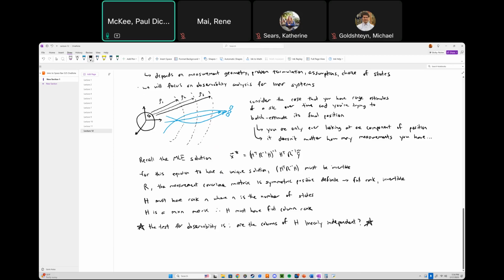It's like, okay, if I only have the range to the spacecraft, it doesn't matter if I have 6 range measurements in 6 states. You're not really measuring 6 different things. You're measuring the same thing 6 times. You're only going to get one component of your position and no information about your velocity. That will not be enough to fully constrain the problem. You will have an infinite number of solutions, and an infinite number of solutions really means no solution. Right? You can't solve that problem.